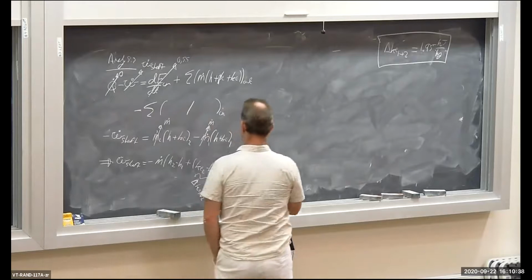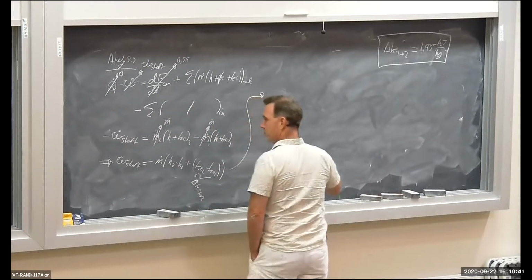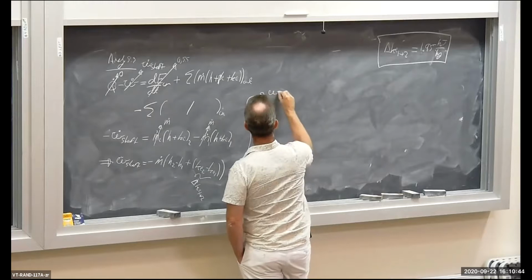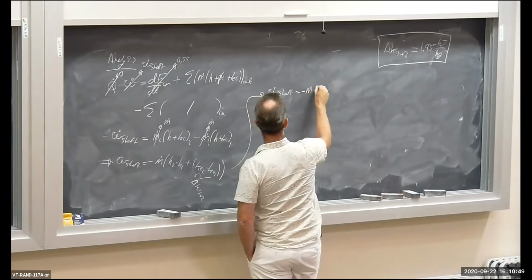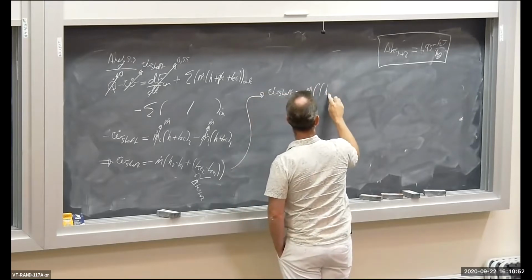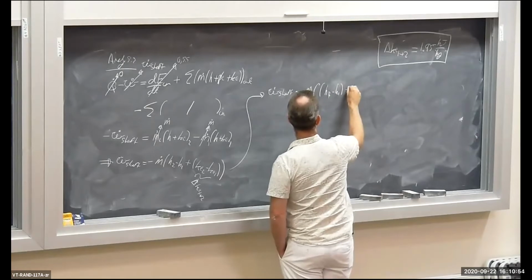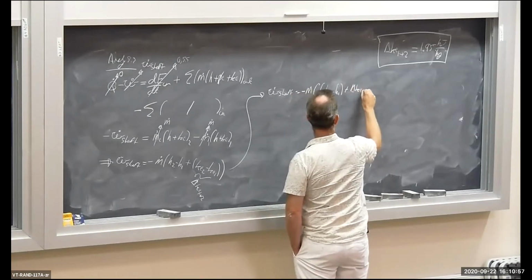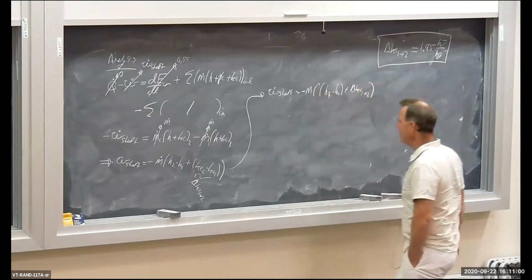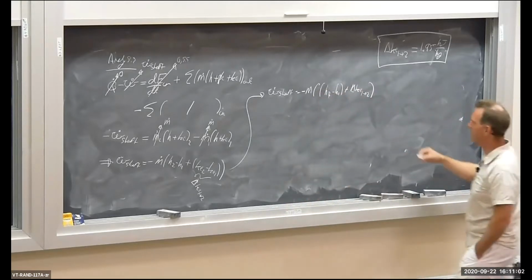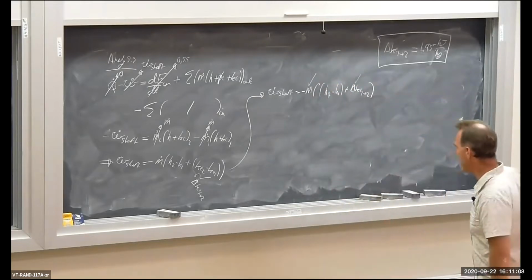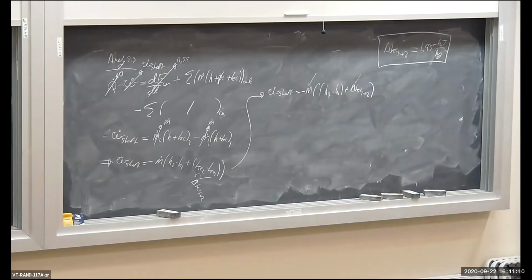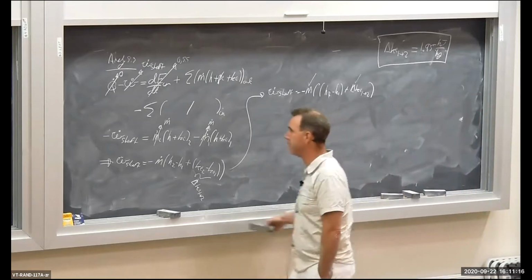So let's write out the final version. W dot shaft is equal to minus M dot, H2 minus H1 plus delta KE from 1 to 2, okay? We've already got this. By the way, we have the mass flow too. Now we need to find the specific enthalpies at the inlet and the outlet.